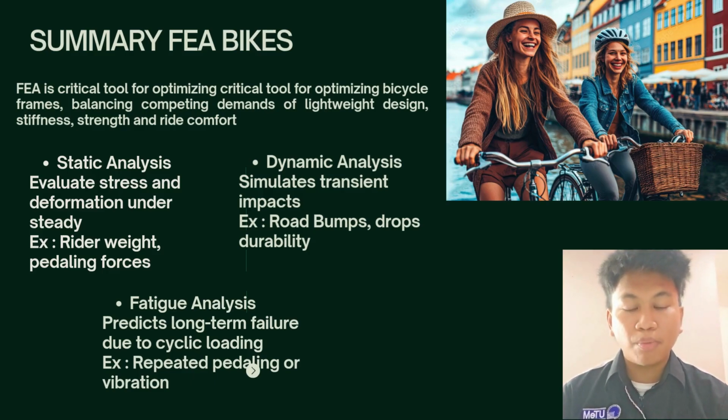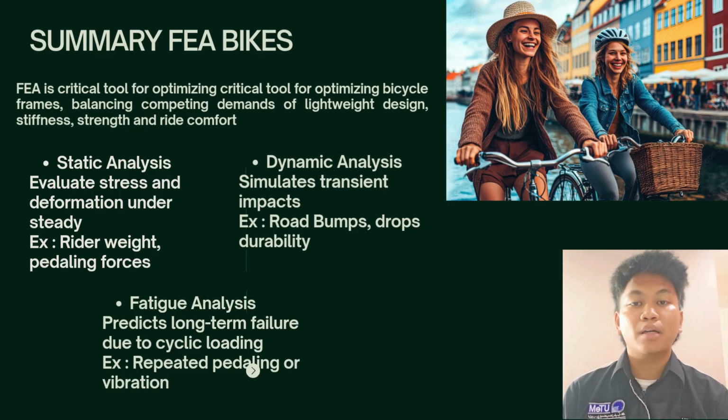The opportunity here is to apply advanced transient FEA coupled with multi-body dynamics to significantly improve the realism of simulation. Closely related is the human-bike interaction gap: rider biomechanics including pedaling force and subtle movements are often oversimplified. Combining FEA with more detailed biomechanical modeling offers a path to truly realistic load simulation.